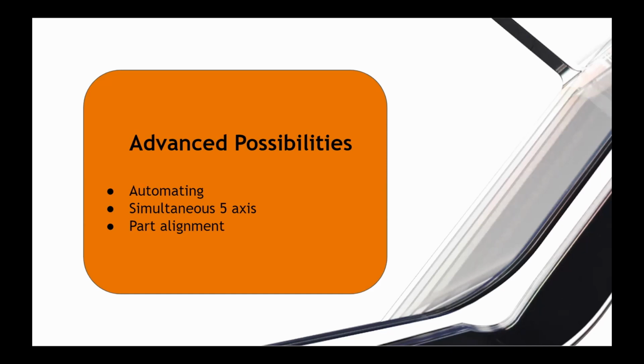So if, for example, you were a company that handled a lot of different parts and very complex parts, and you had a lot of hole features or hole making features on your part, instead of having your programmer sit there and basically reprogram a lot of the things that you've already done in other similar parts, you can use things like the hole recognition feature, where within a couple of clicks, you can go ahead and set up all of your drilling operations, right?